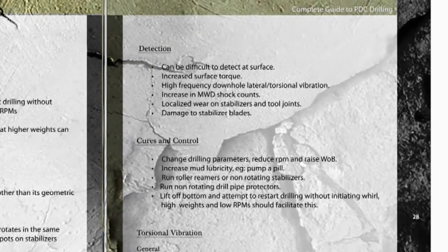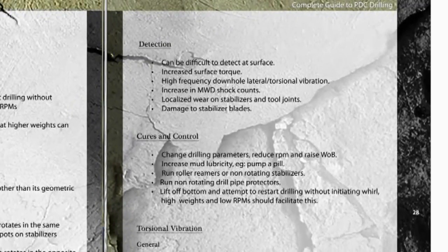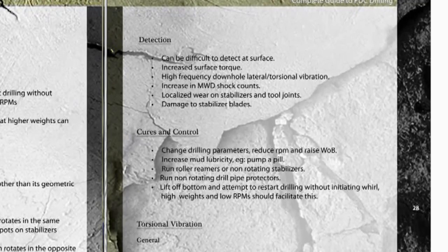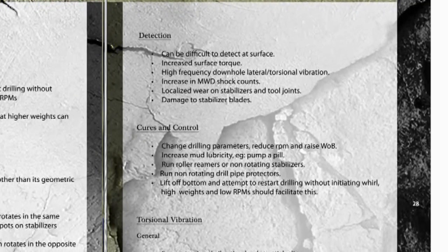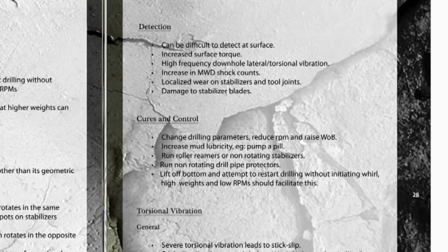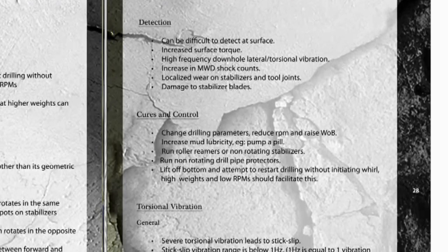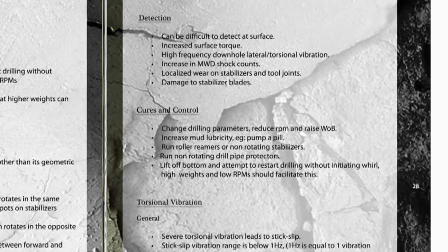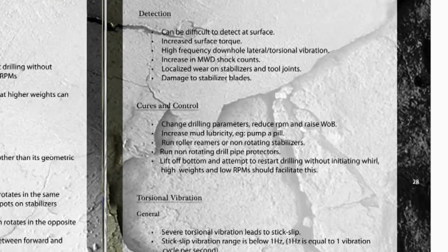Detection. Can be difficult to detect at surface. Increased surface torque. High-frequency downhole lateral torsional vibration. Increase in MWD shock counts. Localized wear on stabilizers and tool joints. Damage to stabilizer blades.